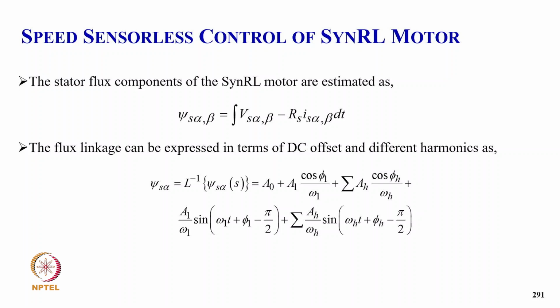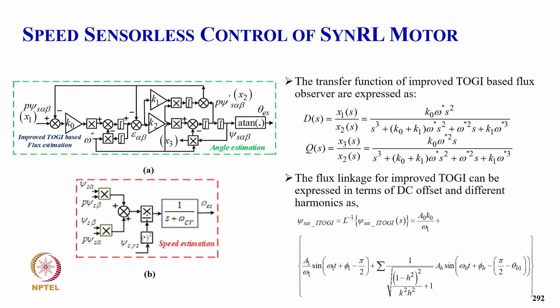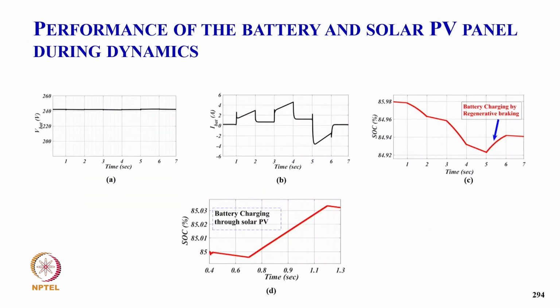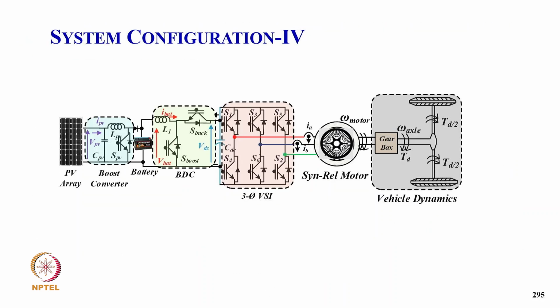And this is the estimation of the flux, and the flux expressed as a typical DC component, and then with the filter we remove the DC component. These are the filter equation, and this is the performance. Of course, during typically acceleration, deacceleration with the regenerative mode, and during starting typically, and the different parameters.